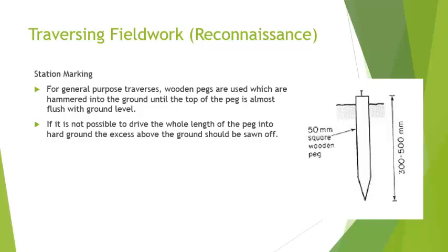Or other options than a spray can. On a site which has trees, caution tape can be used to assist in finding the stations. Or on plain sandy ground, a stick about half a meter tall can be used together with caution tape wrapped at the top of the stick. These are all to assist you to find your stations later on.